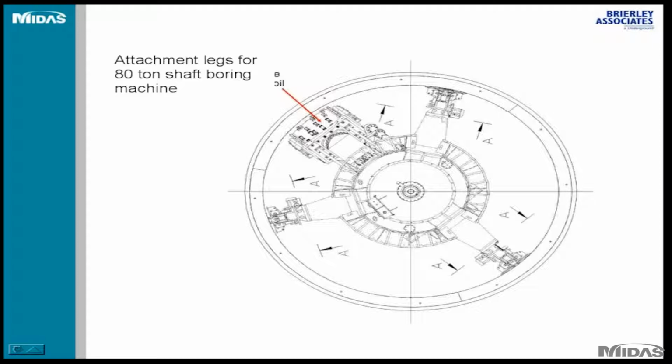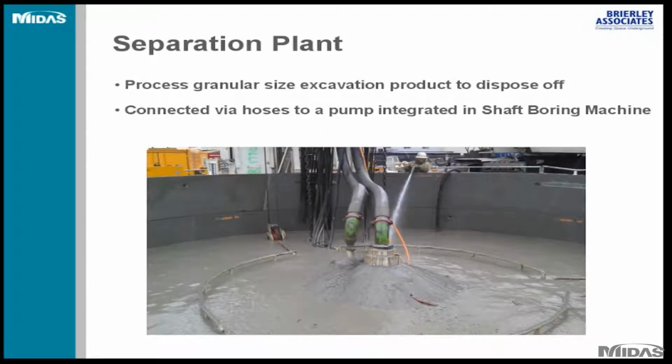So you see there are 3 legs, and a telescoping arm, which is used to cut the soil. And again, remember that this shaft is connected to the very top. So the shaft boring machine is independent of the sinking unit. They are 2 separate systems, not attached to each other. Of course, there are some controls that go to the control unit, but they are independent.